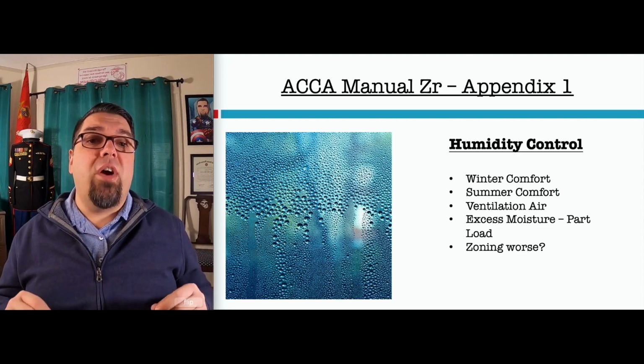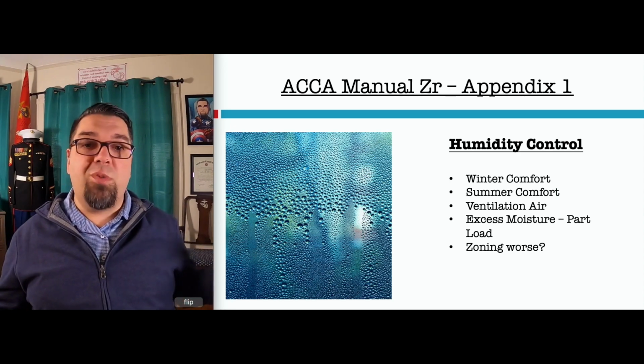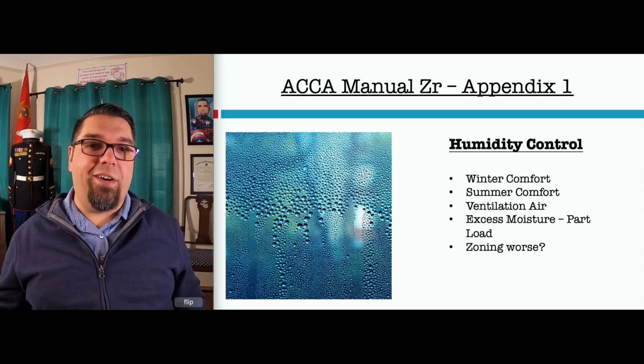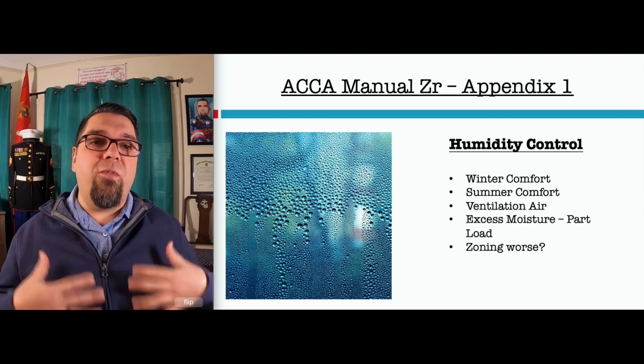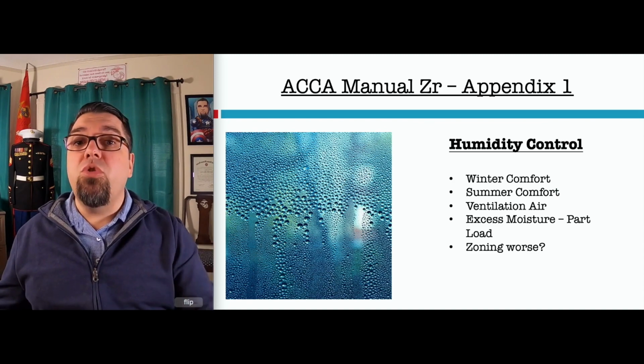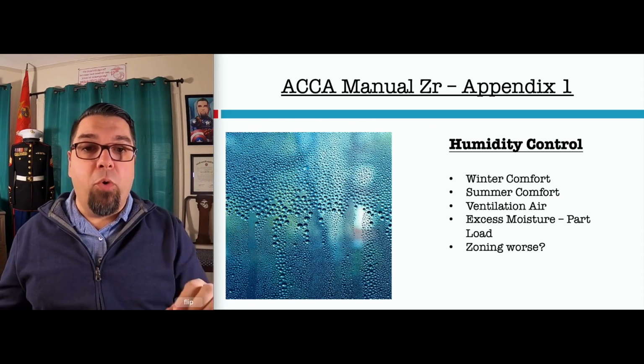And not just try to zone a section of the home thinking if I can force more cold air there, it's gonna be better. Bigger's not better, all right? We gotta control the condition that we feel for comfort, all right? Humidity is a huge part of that. I know I'm harping on this. I wanna make sure you guys understand how important this is, all right?